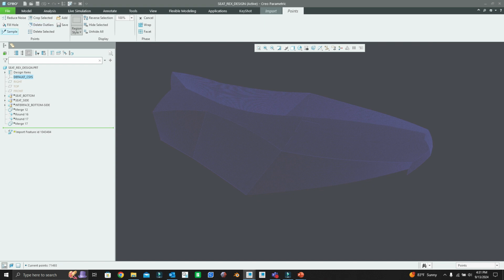The first thing I'm going to do is use the sample tool, and if I select the sample by curvature node, based on the percentage that I give it, it will reduce points in the more planar surface areas that don't really need more points to define the curvature, and it will either keep or add points in the areas where there is more curvature so that it's defined enough to create a high quality surface in those areas. So I'll use the 85 percentage here and click OK. You'll see it update there in front of us.